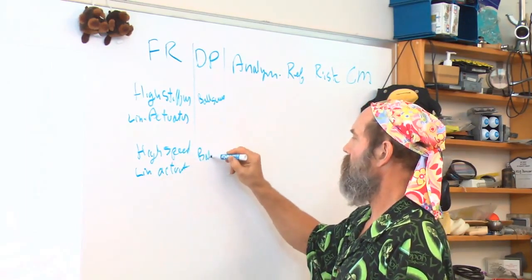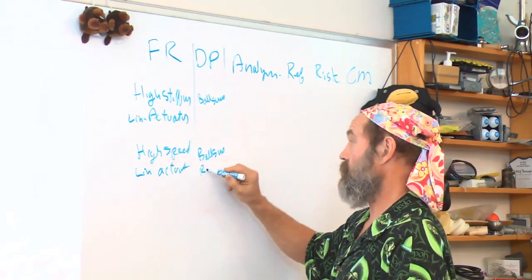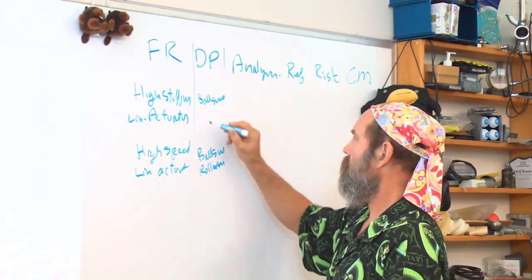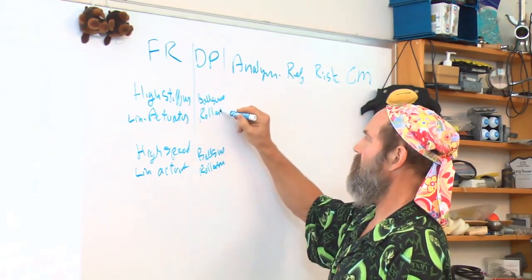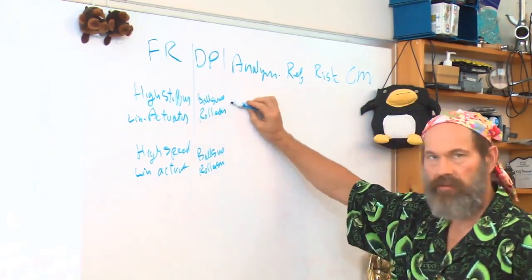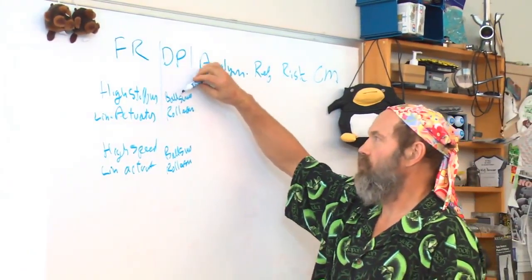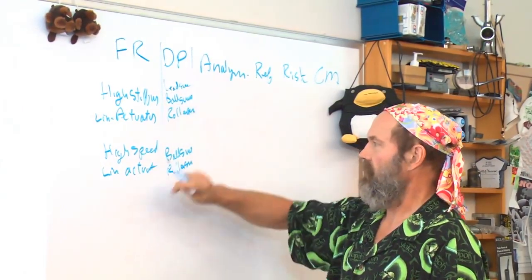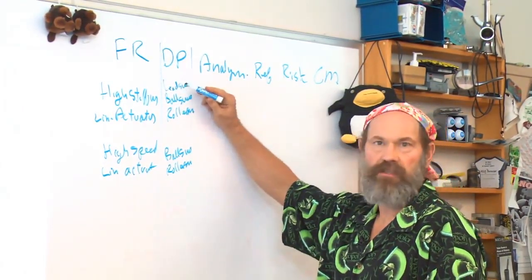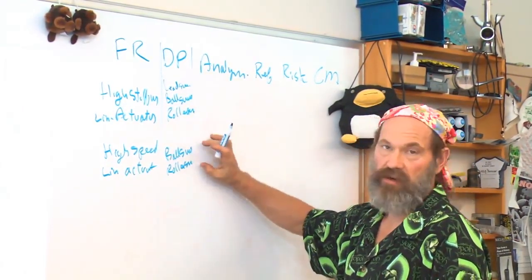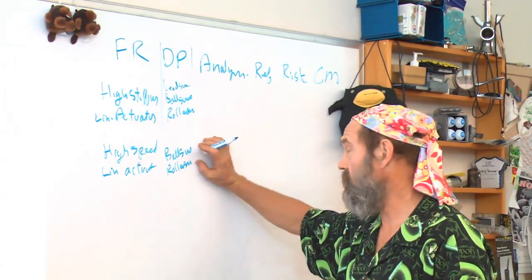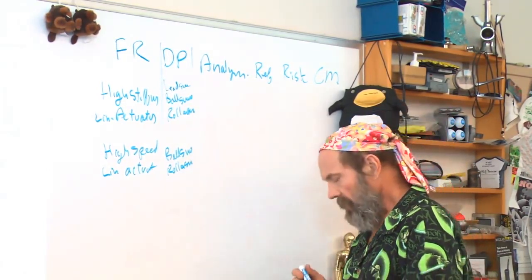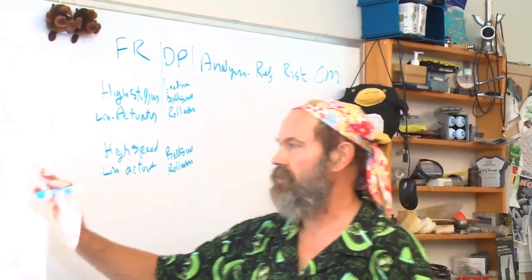Ball screw, or maybe a roller screw. We can decide later, but basically we're going to use a rolling element system. You could use a lead screw here, but when I go to high speed, that kind of nixes the lead screw in general. You're much better off with a ball screw because of much higher efficiency. And you merrily go happily designing along.